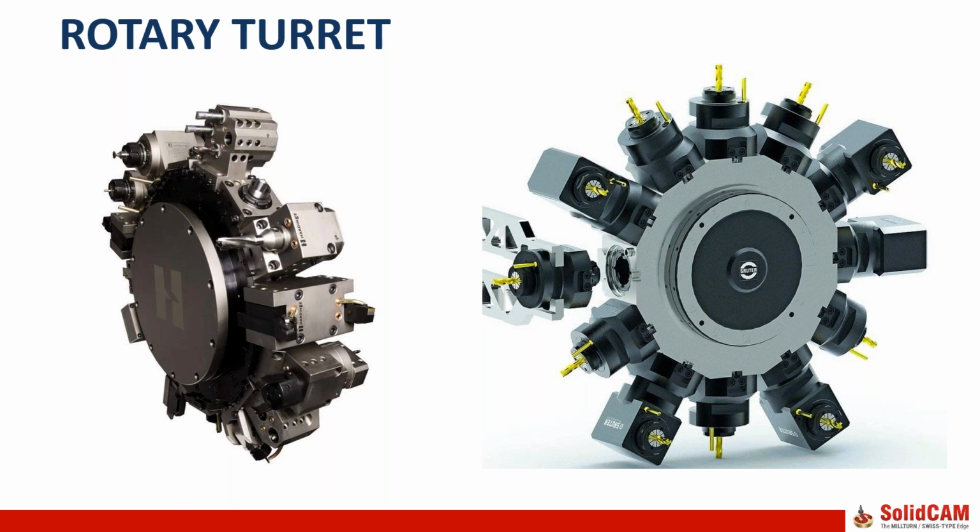And regardless of whether it is a turning tool, which is a fixed tool bit, or a driven tool, like any milling tool, right? So this tool holder, which is rotating, holds very different tools. So it's both a storing device and also a cutting device. So this is a tool post on a modern machine.